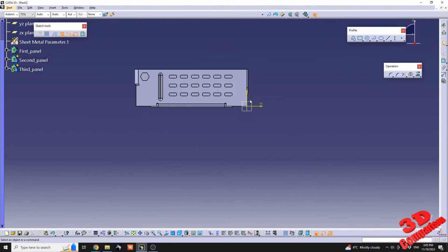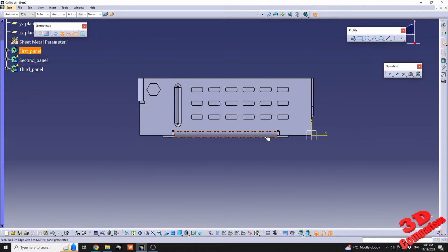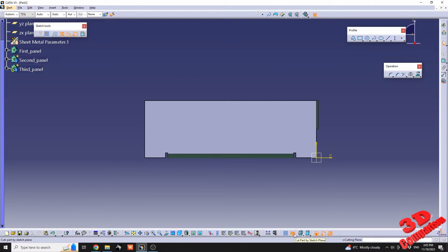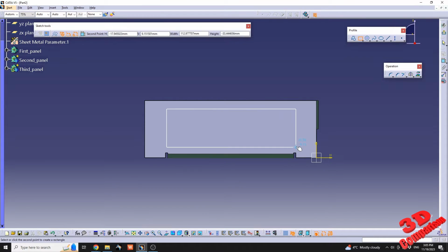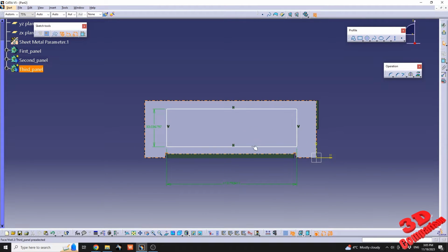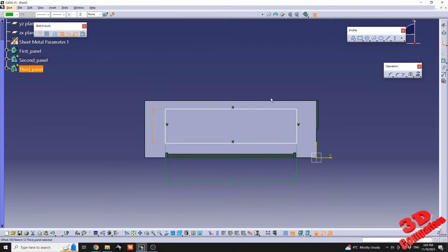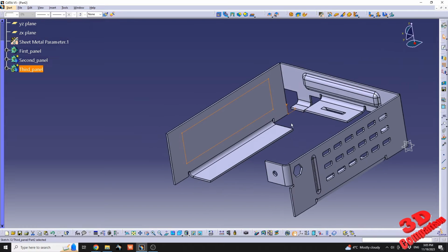I will just do something quick. So I selected the inner face. Afterwards, go to cut part by sketch plane. I will just draw a rectangle. If you want to, you can have that constrained. I will just put some nominal values over here and have this cutout.